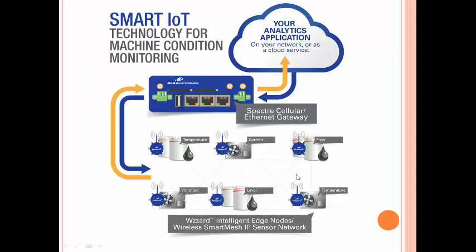Now the buzzword of this generation, of this electronic generation as I would say, is the IoT, the Internet of Things. So using the smart technology, how can MCM be used? We can place the PCI 4462 connected to the device we want to monitor and connect that to an Ethernet gateway or a Wi-Fi gateway, and we can access it from a remote location. So many such things such as the current, temperature, vibration, noise level, flow, everything can be monitored.